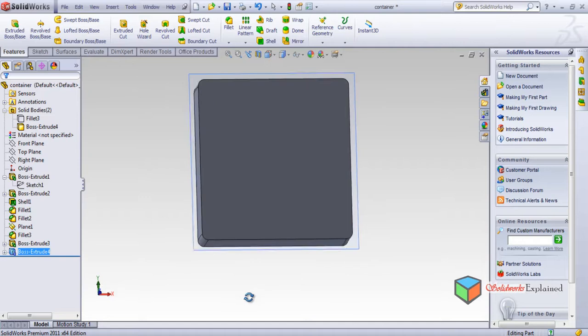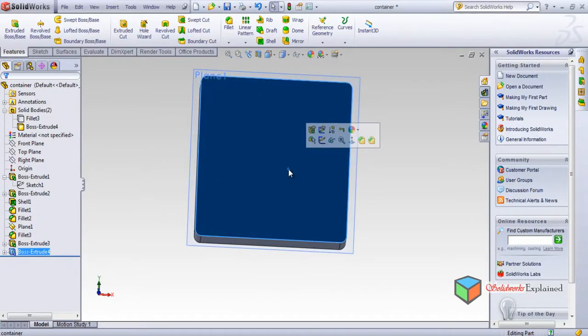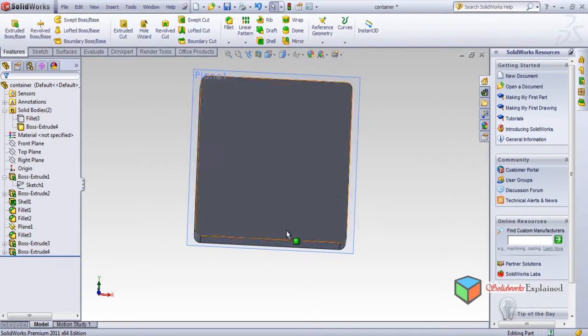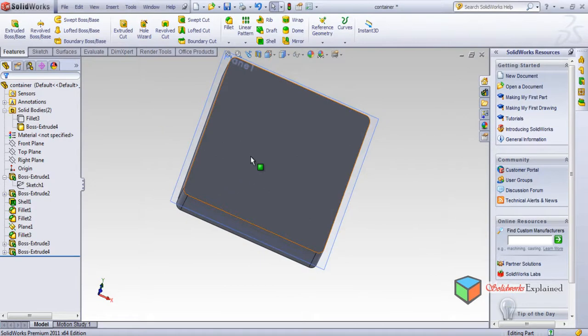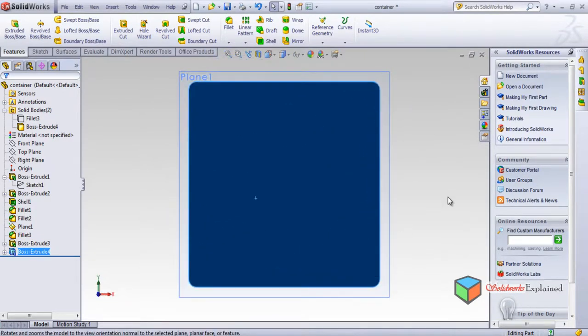Now after merging, I want to make something over here on this plane also. So making anything on this plane is like going to edit sketch. Look, it goes so back. Be careful, back, and then like this, and make it normal first. Yes, after making it normal, we will be making something on this.